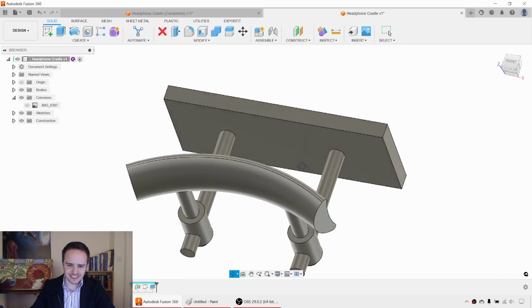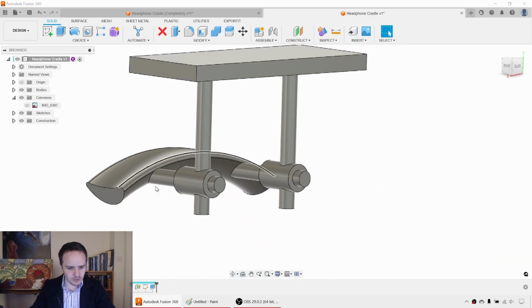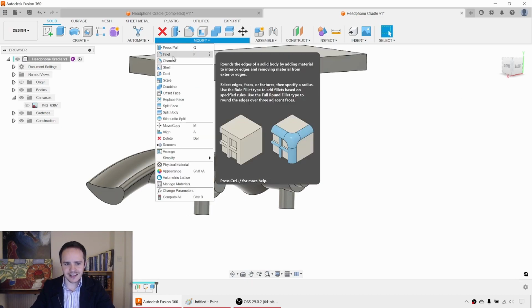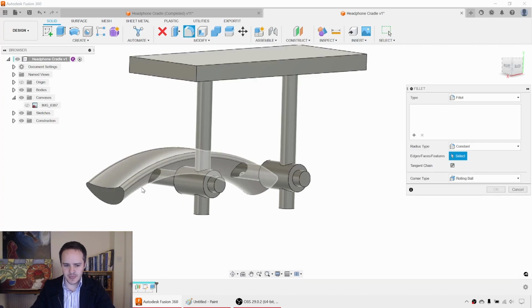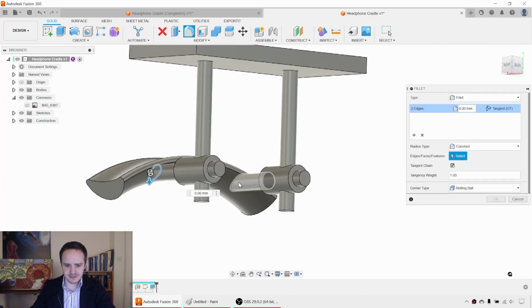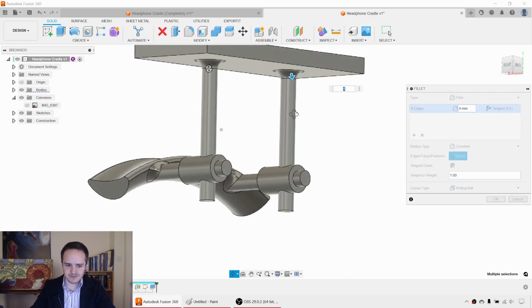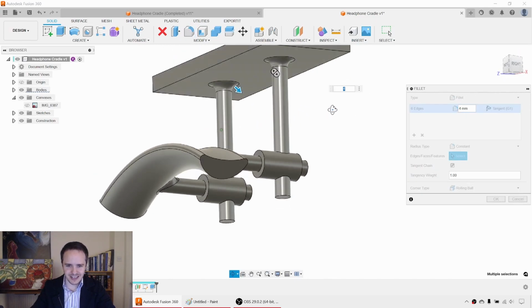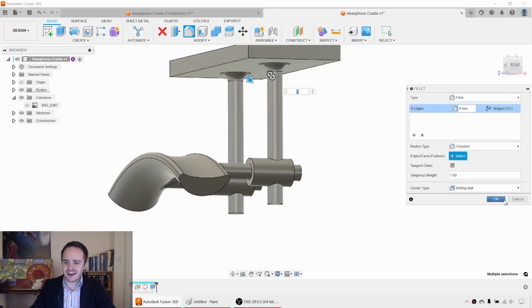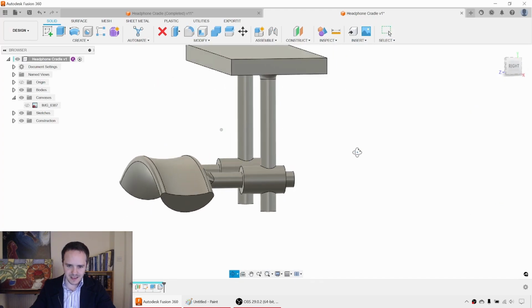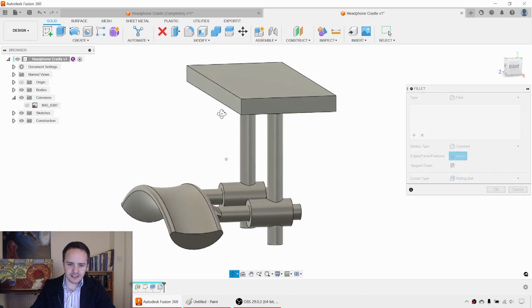Lastly, well, not lastly, we'll need to add in some bolt holes, and then we'll add in some fillets and chamfers. So let's add the fillets first, they're easy. We'll come along here to modify and click F for fillet. And we're going to add fillets 1, 2, 3, and 4. These should relieve some stress when I eventually abuse this thing.